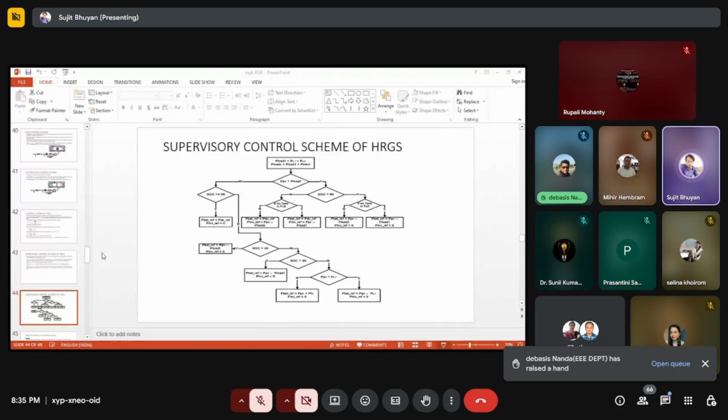And here is the subplot of the current waveform, which I have taken from some time period to some time period, and this is the THD analysis. THD is 1.0, and somewhere it is a little bit more. And this is the power waveform of the variable load. So, for the overall conclusion, I have told you this is the load of HRGS, the constant load and the variable load. Whatever I told you, I have done under the THD analysis, and this is the overall conclusion.